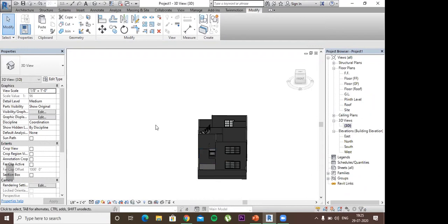So our first doubt is how we decide how much dimensions should be given to kitchen, bedroom if we are getting only dimensional plot area. That we have already talked about. It comes with experience, but I'll give you some standards. Generally you will find this in the building bylaw of the state in which you are living. They have a rules panel of how much gap you have to leave in the veranda, how much should be the minimum of a kitchen, and it also depends on the plot size.